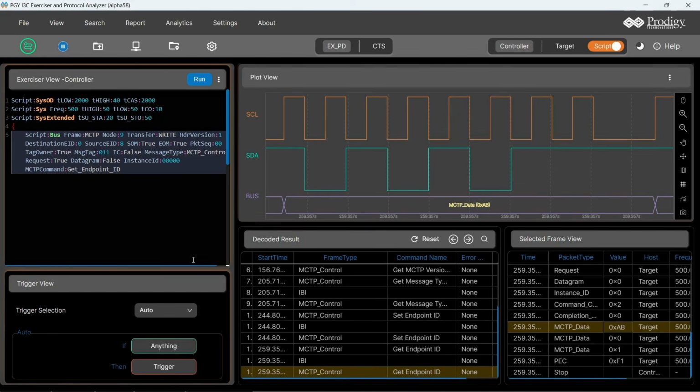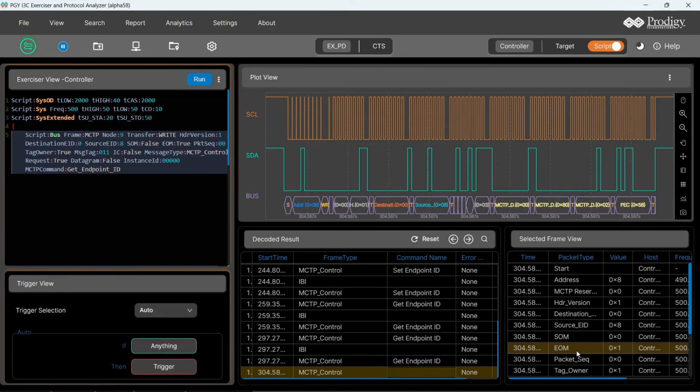When an MCTP packet has a SOM or EOM bits incorrectly set, the individual response packets are silently discarded by the endpoint under these conditions. In this case, the target has silently dropped the response packet.